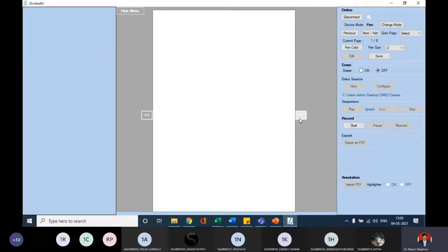Once you got this value of alpha, now I'll try to write the value of MT. MT is equal to m k square alpha. Here the other part of the knowledge required is the units, guys. You should not forget about the units. Alpha is in radians per second square, and mass is in kg. What should be the unit of k, man? He has given k as 125 mm. Should I leave it as 125 mm or should I convert it to meters? And MT I need in terms of Newton mm. So k should be in what?